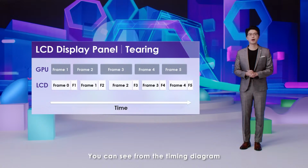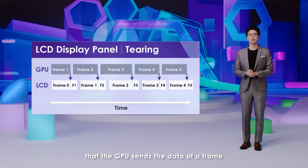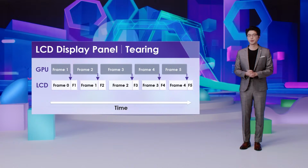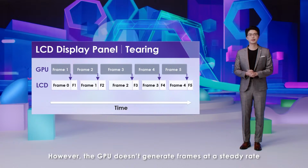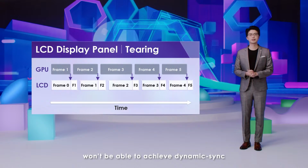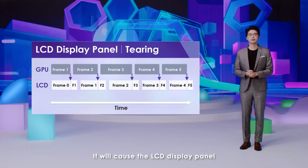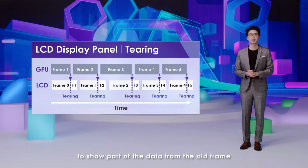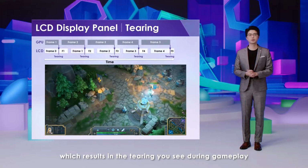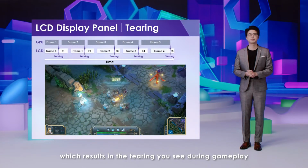You can see from the timing diagram that the GPU sends the data of a frame to the LCD display panel immediately after the GPU generates it. However, the GPU doesn't generate frames at a steady rate. An LCD display panel with a fixed refresh rate won't be able to achieve dynamic sync. It will cause the LCD display panel to show part of the data from the old frame and part from the new frame, which results in the tearing you see during gameplay.